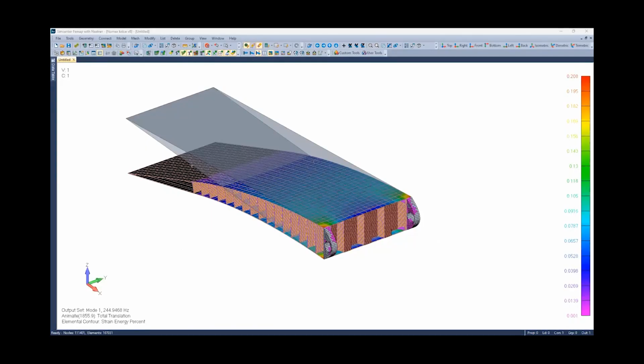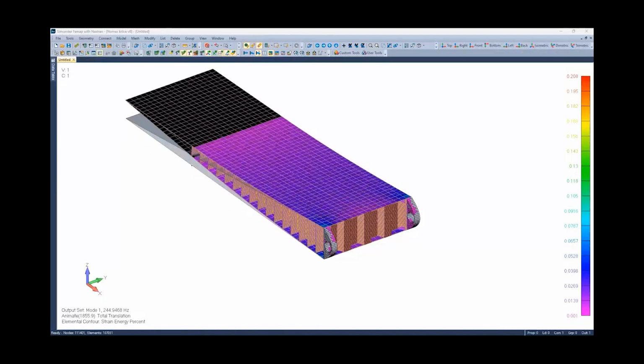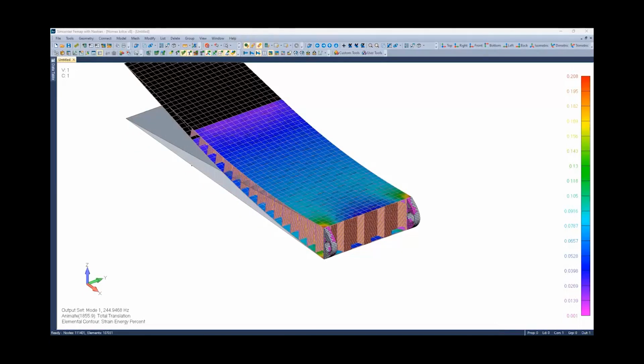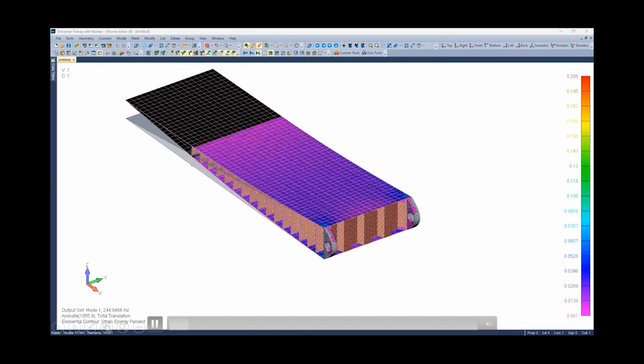Nevertheless, we were chasing, first of all, the first two frequencies. The first one is in bending, and this is the one we are actually looking for. It is a relatively complex model, created with the approach that I was explaining right now, to obtain the first frequency, which is the first dynamic analysis, the modal analysis that we always do, coupled with, of course, chasing the next frequency, which is the frequency in torsion.